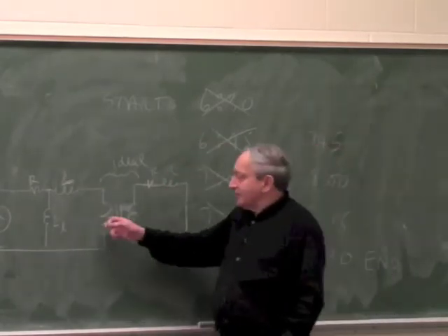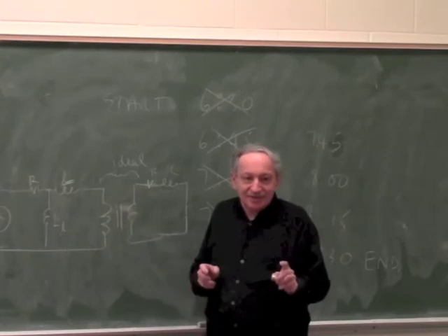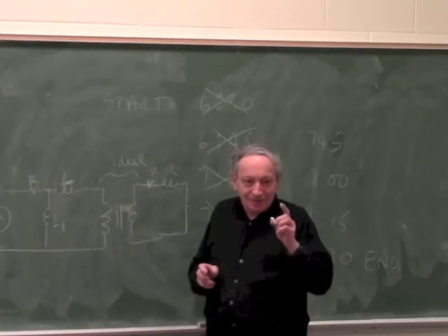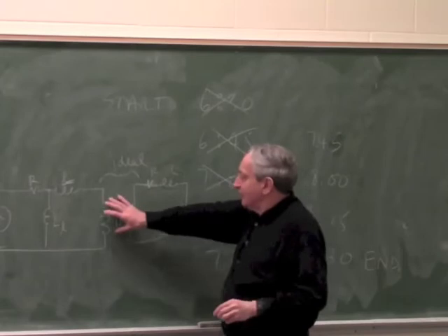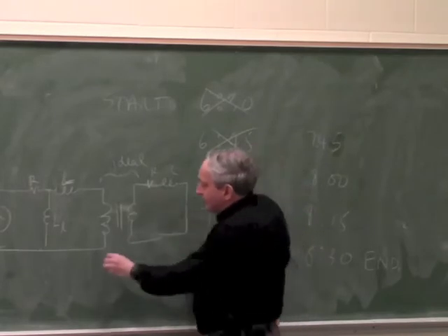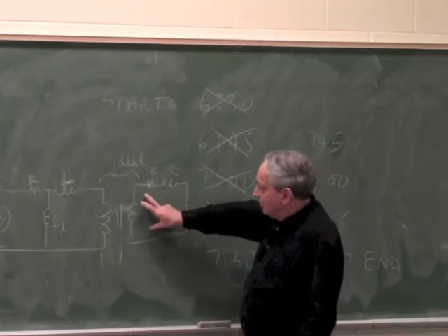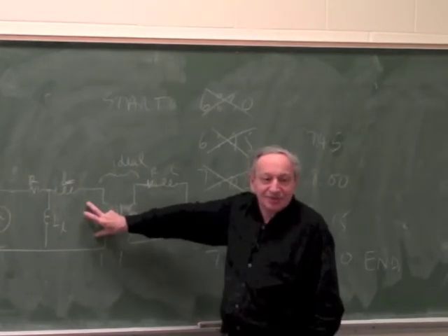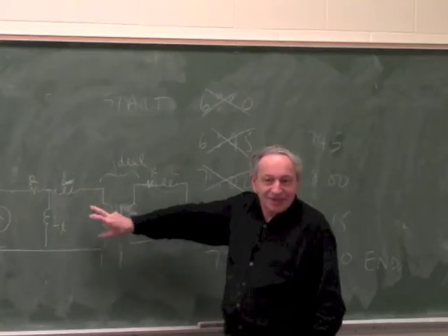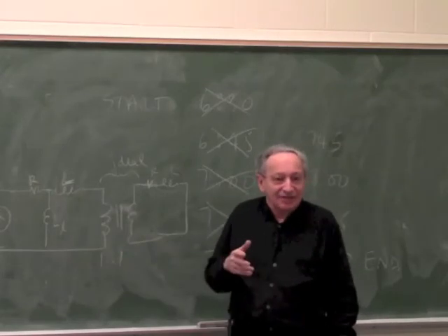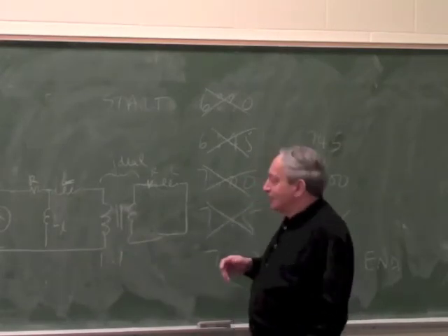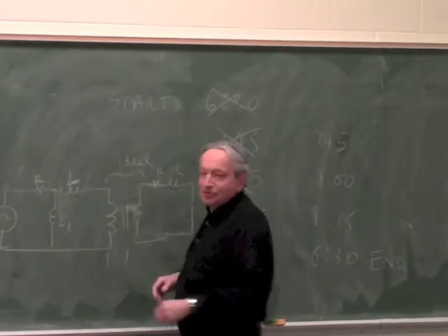Because you increase the frequency, this becomes a concern. Because an ideal transformer has no inductance. You have to think about this for a moment, because an ideal transformer just reflects this resistance. If this was a one-to-one ideal transformer, and you put a resistor here, you just see the same resistance on this side, you don't see inductance. So the inductance is a parasitic effect in the transformer, which comes from flux which doesn't engage both coils.